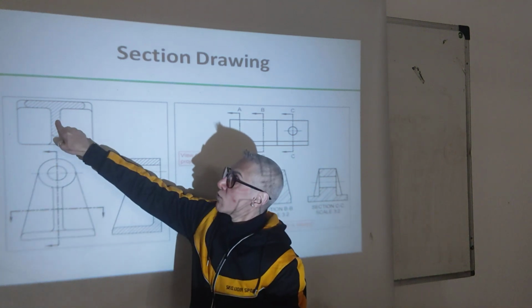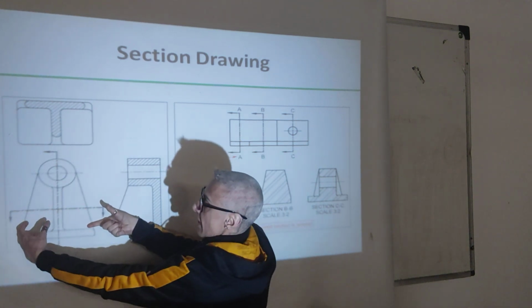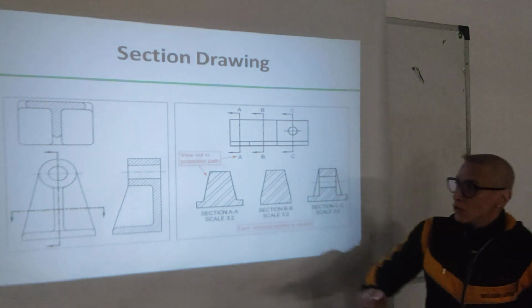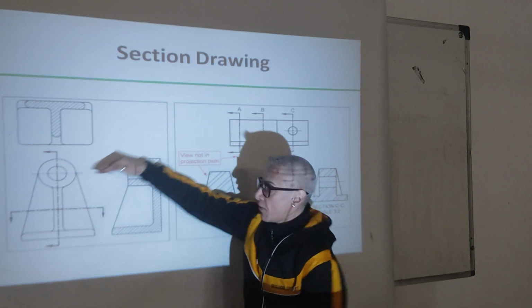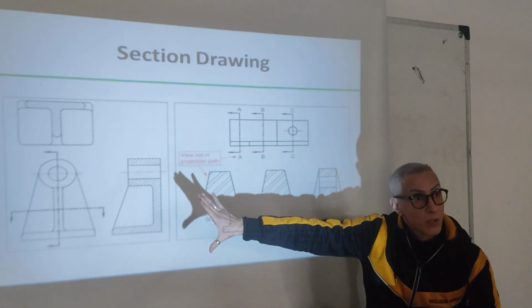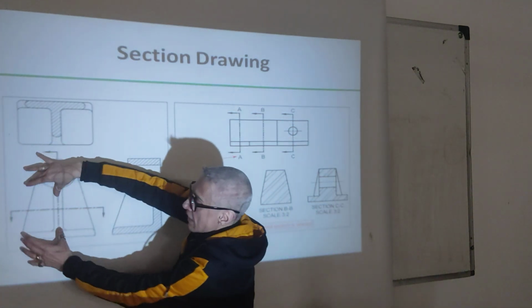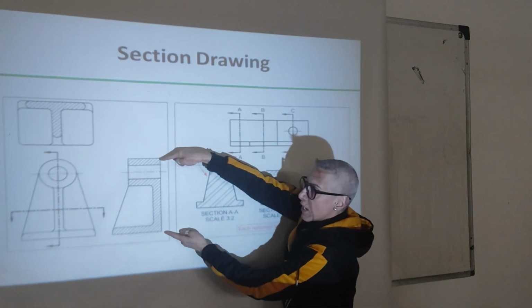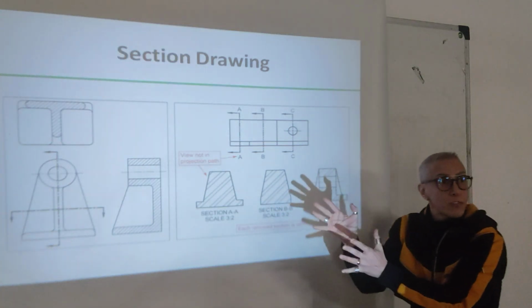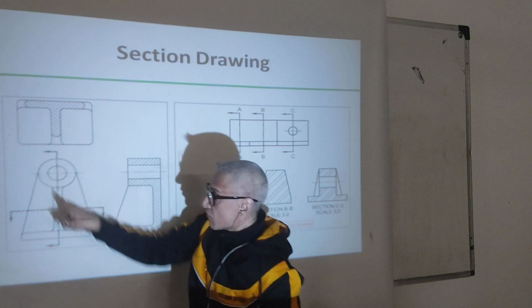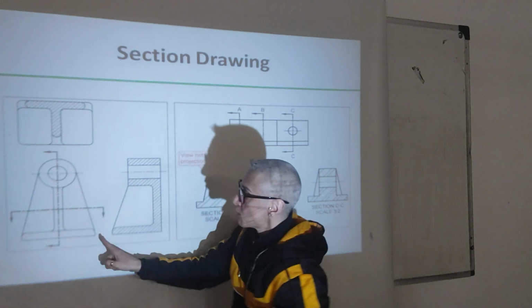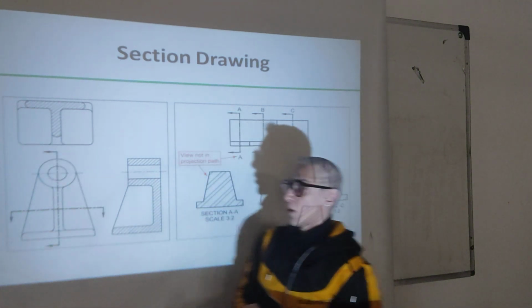It will be BB, and it will be shown here, meaning this part we are taking, rotating it, and putting here, okay? So, usually when you cut in a certain way, the object shown at the section is aligned with the view, okay? So, this is here, for example, taken, this part, rotated, and put here. And all of these are aligned for easy vision, okay? So that we can understand what's going on. And this section here is this part cut, so this part deleted, this object taken and put here, and everything aligns, okay, again.